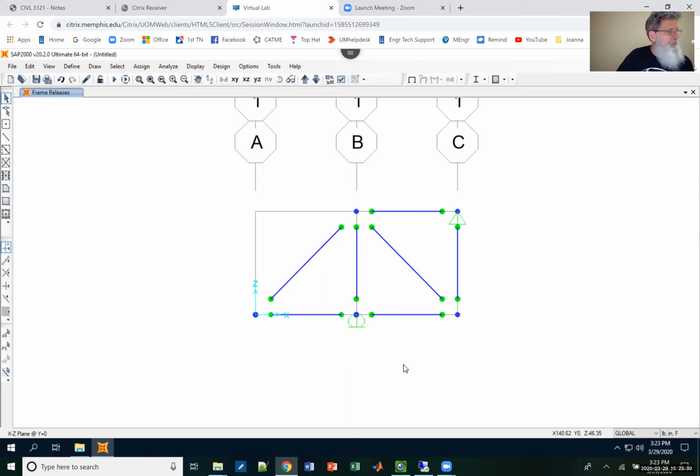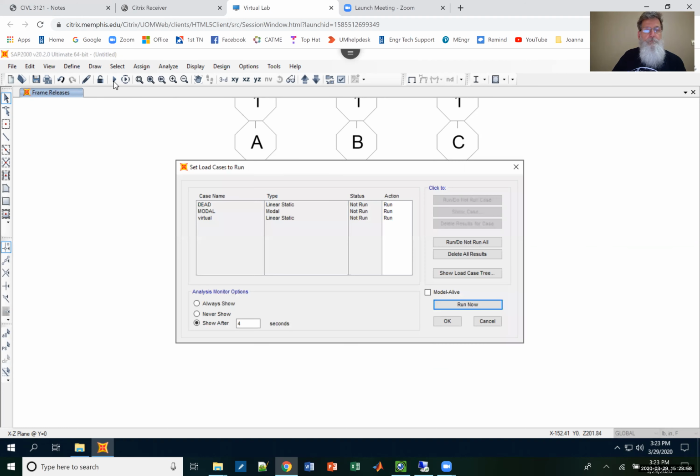So now what I need to do is assign those cross-sectional areas. But really, I don't have to worry about that, okay? The area and the E value will come into our calculation. Remember, when we do virtual work, we're going to sum up real, virtual times length divided by AE. Here in SAP 2000, I don't have to do anything. I'm just going to find the forces. So I'm pretty much ready to go. So I'll come up here and say run.